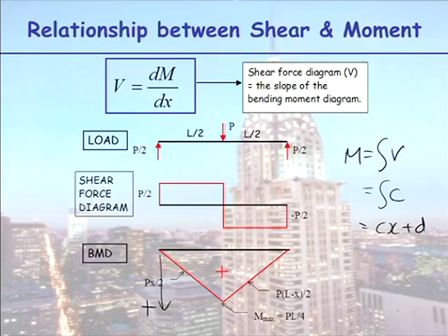So how did we draw this bending moment diagram? We knew our bending moment was 0 at the two supports. We knew we had a downward slope because our shear force was positive. We know we have an upward slope because our shear force is negative. Join the dots. It's a dot to dot. You go, okay, I know it's 0 here, it has to slope down in a linear fashion, and then it has to slope up. So I can get the shape. The only thing left to get is what's that maximum value there?